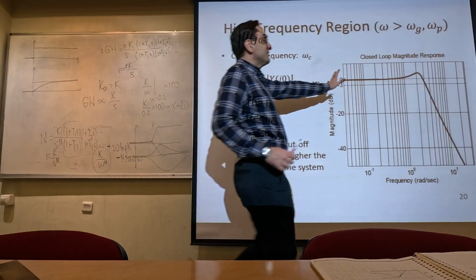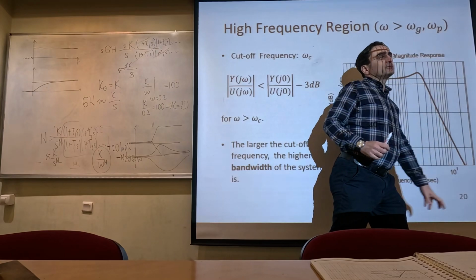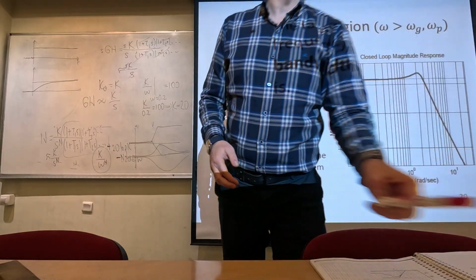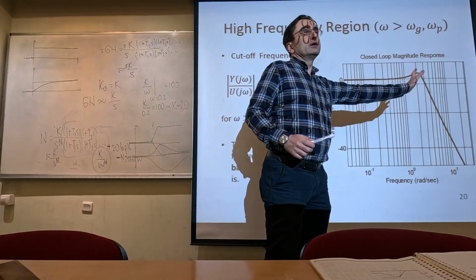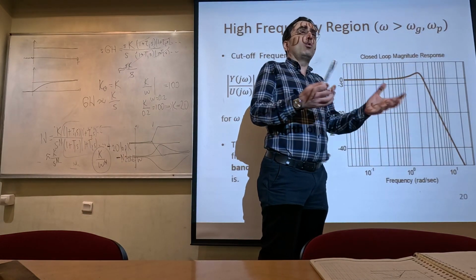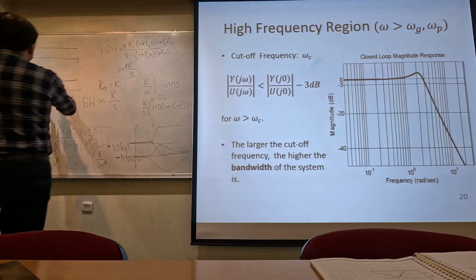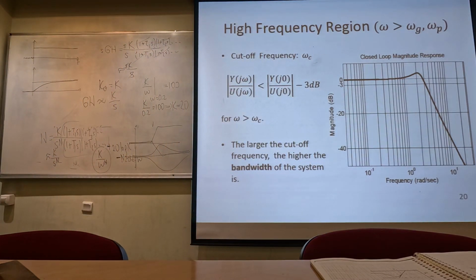So if I increase the cutoff frequency of the low pass filter, what type of response would you expect? If I increase the cutoff frequency, then we start to get an almost all-pass filter. What is going to change in my response? Is it going to be closer to the unit step or further away? Closer to the unit step. If I increase the cutoff frequency, the system is actually going to be faster.